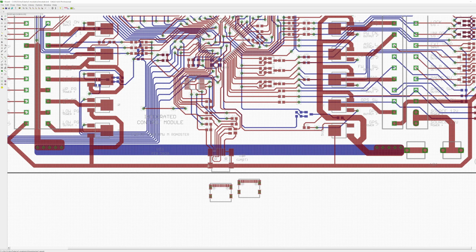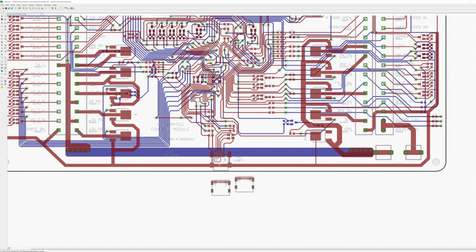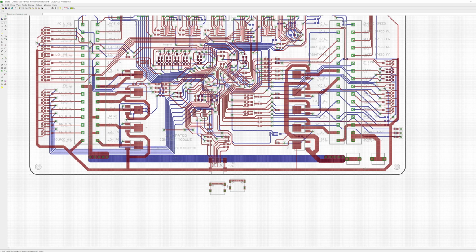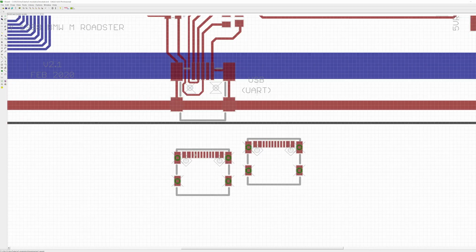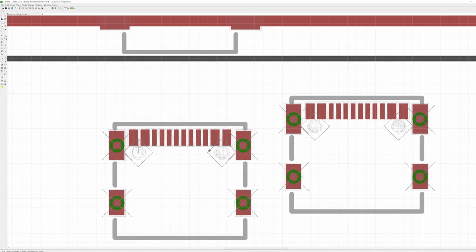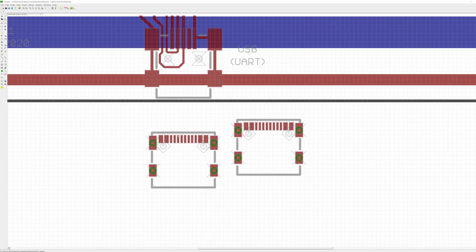So I've saved this copy of the board, and we'll modify this file as we build out our PCB for the project. But now I've got this model built in my Paint/Photoshop paradigm so that I can copy this into other projects. Now, I will probably use it in at least one project before I copy this model out, because I might need to make some tweaks. I might need to change drill sizes. I might need to slightly modify the positioning, but we were basically just tracing over the model that we downloaded, so it should be pretty close.